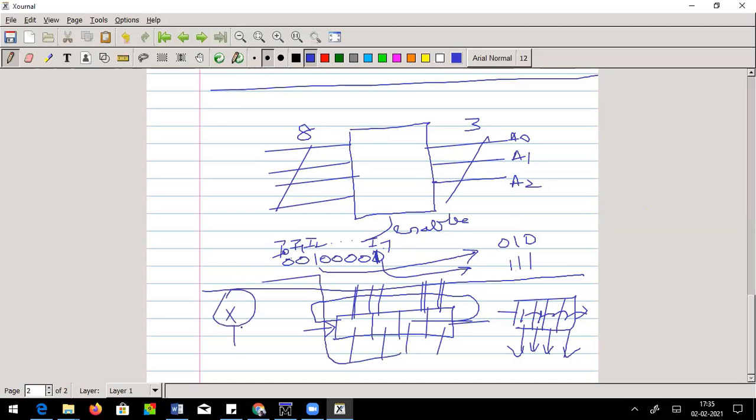One multiplication operation can be equated to a shift and add technique, or you can replace a multiplication by a shifting technique, right? This is like 2 raised to the power of n. For every shift, you can move it through. If you want to multiply, you shift it towards your right. If you want to divide, you shift it towards your left. This is what a barrel shifter does. You could see in your books a barrel shifter, which is also used in multiple places for system design.